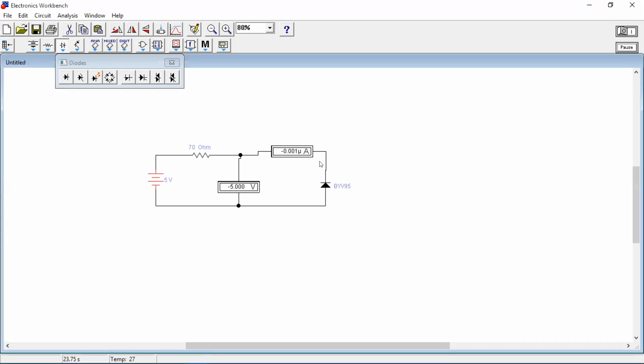If in forward bias, we can get the current after some voltage. This voltage is the barrier voltage. In a silicon diode, we can get a huge current at 0.7, after 0.7. In reverse bias, we can't get the current, even if we apply more voltage.